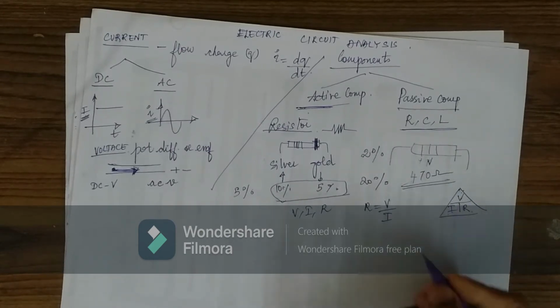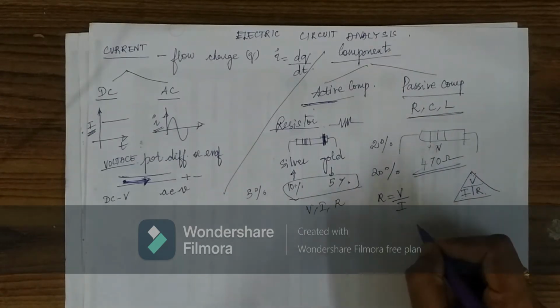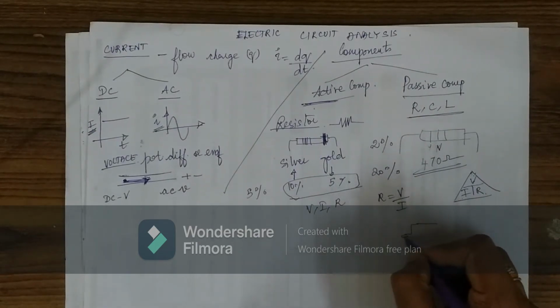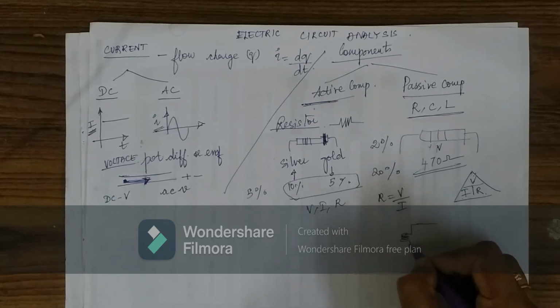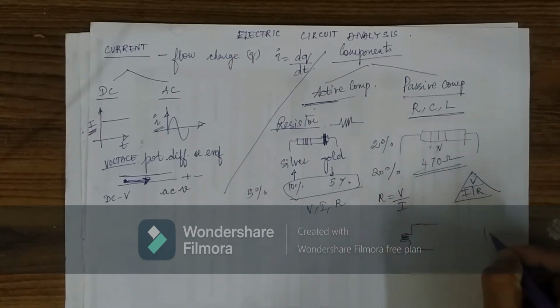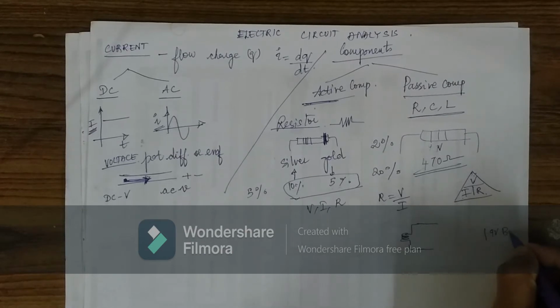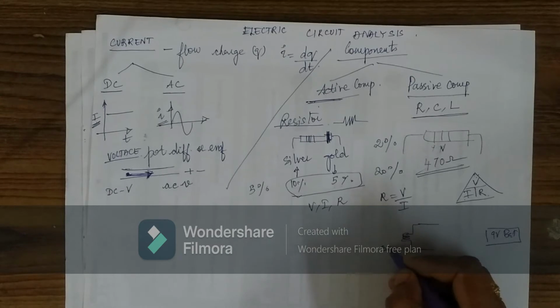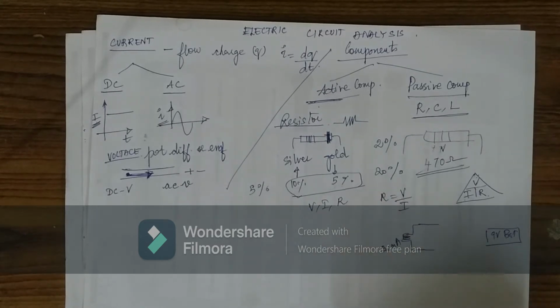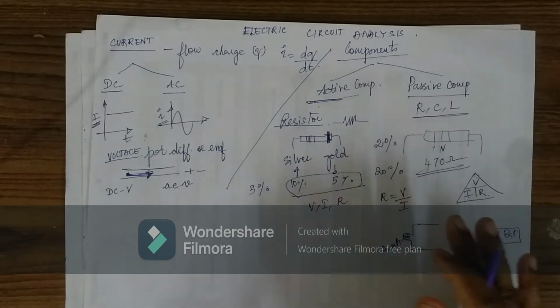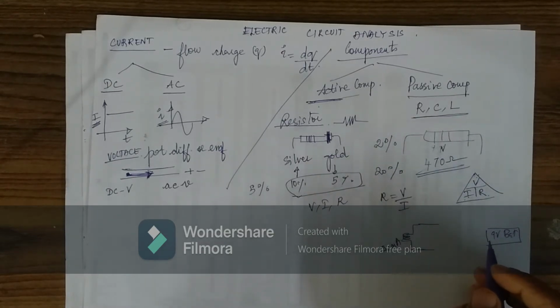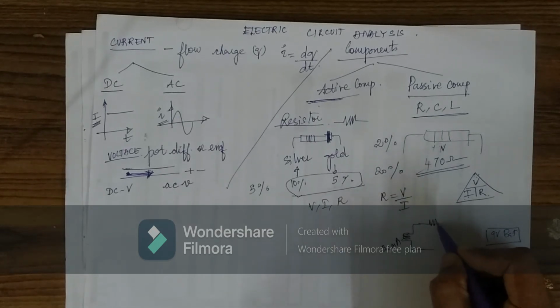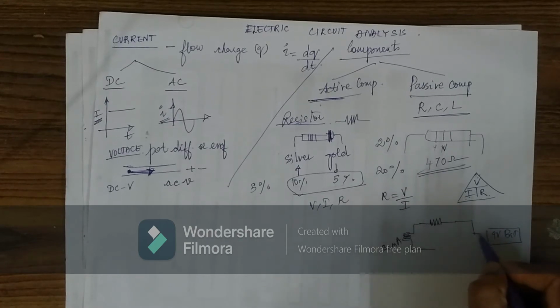So let us take an LED lamp, LED light, right, and a 9 volt battery. The specified maximum current for this is 30 milliamps. Now, if we connect this battery directly to the LED, it might burst instantly. So we need to connect a resistor in between in order to limit the current.